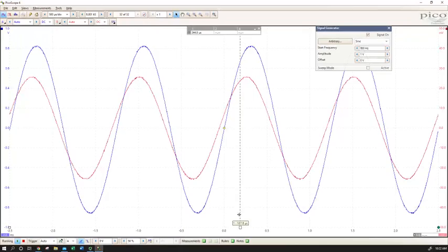Basically, if we were to take a spot here where our trigger is, our whole circuit is crossing the y equals 0 axis here on the blue, so it's heading up, and you can see our red signal did that at an earlier time. So the voltage drop over the resistor is leading that of the whole circuit. We want to find the frequency for which neither one is lagging or leading. We want them right on top of each other because that corresponds to resonance.